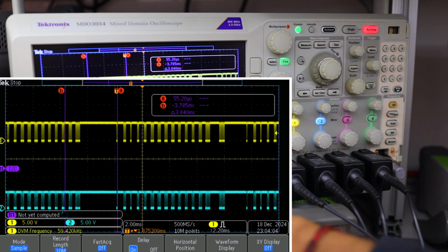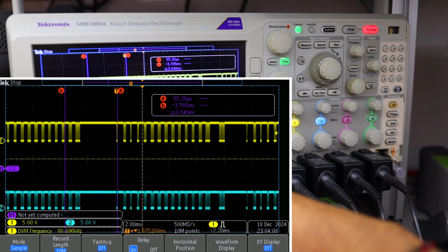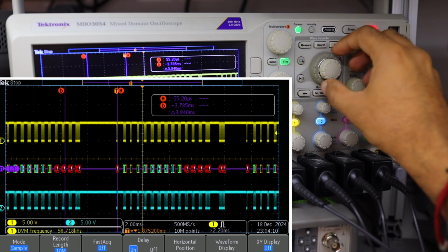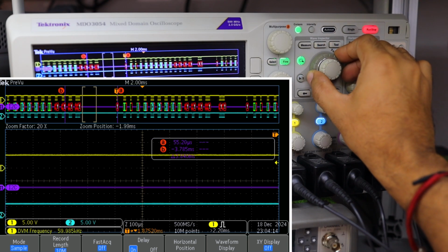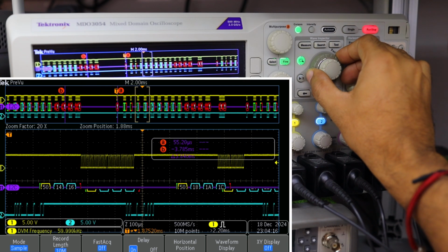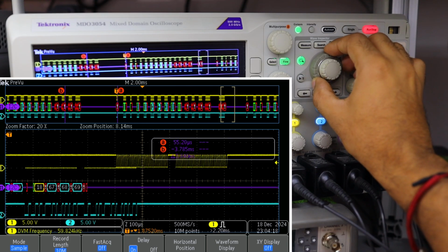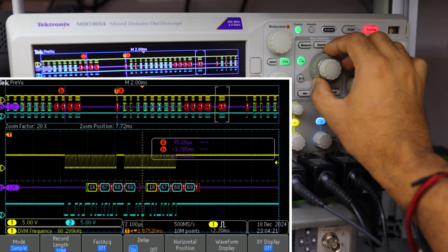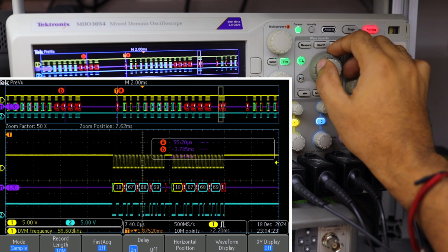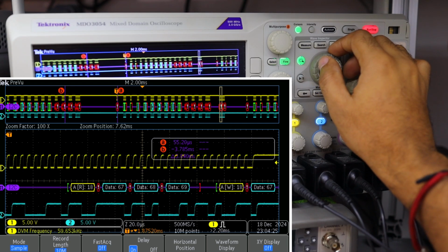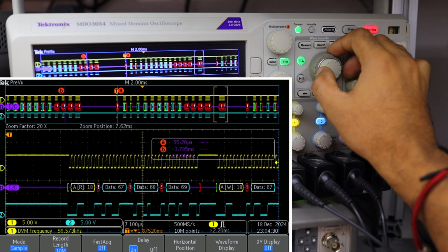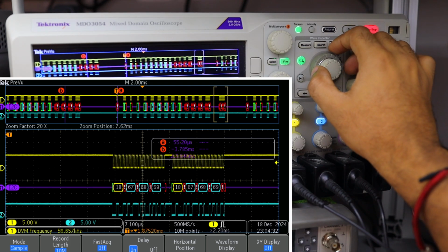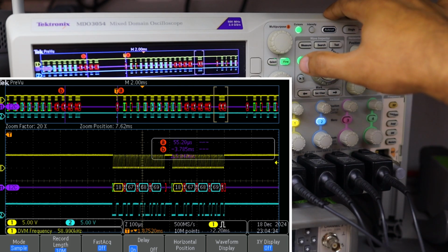It will take some time. You see it down there, this arrow is rotating, bus not yet computed. Because the oscilloscope takes some time on 10 mega sample to decode the memory, I'll zoom in this time as well, and we will look for that weird packet which doesn't get repeated all that often. So we are here and it says 186767, and we will trigger on that and see how it looks in the trigger and if it stabilizes the trigger as we did with the RTB2004.